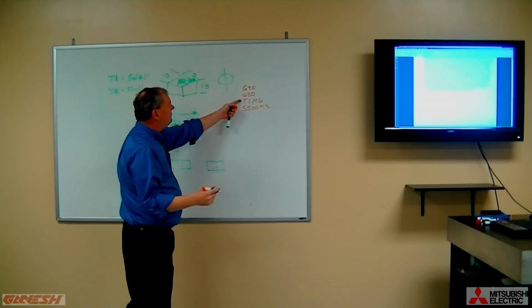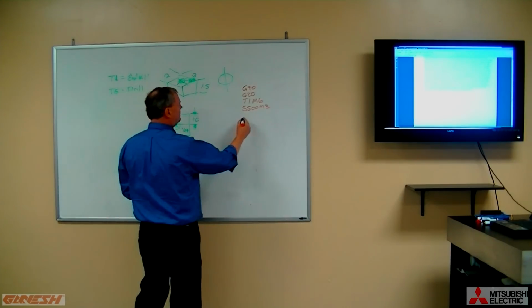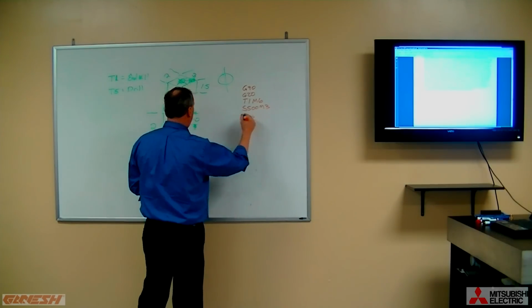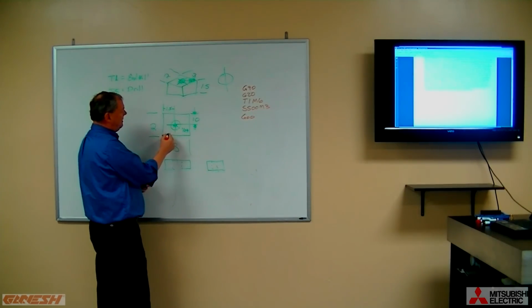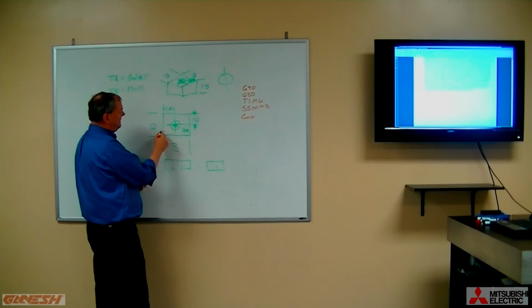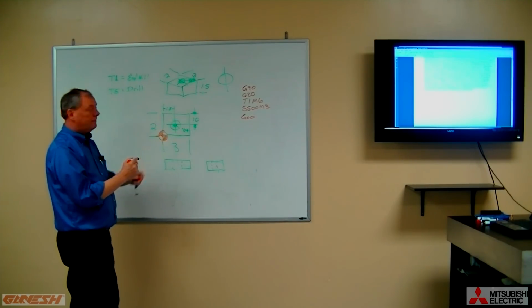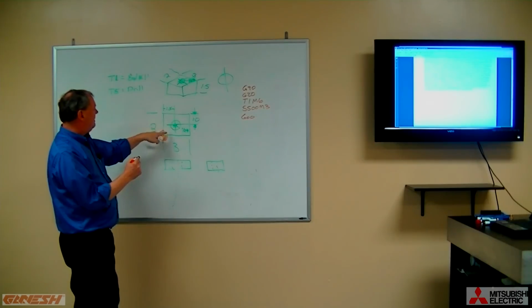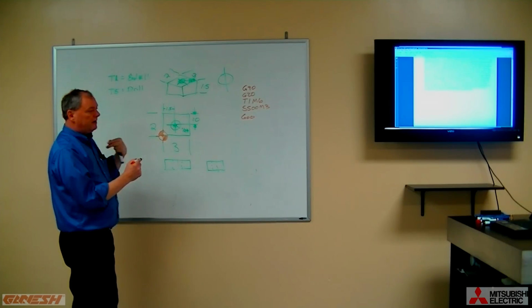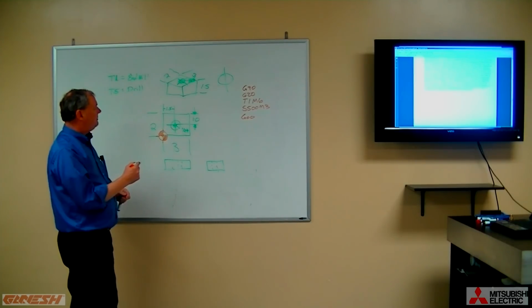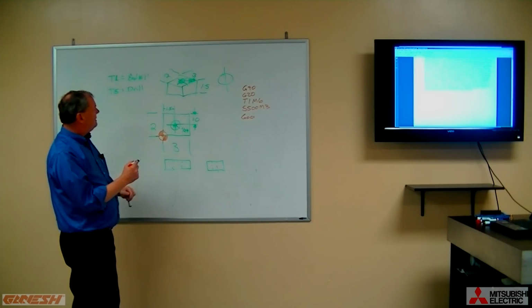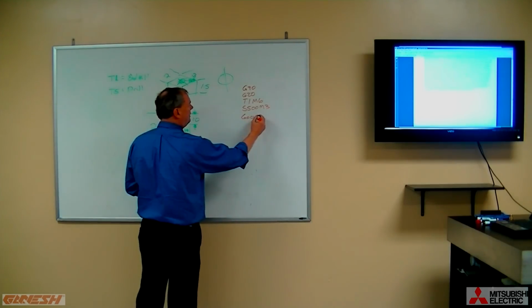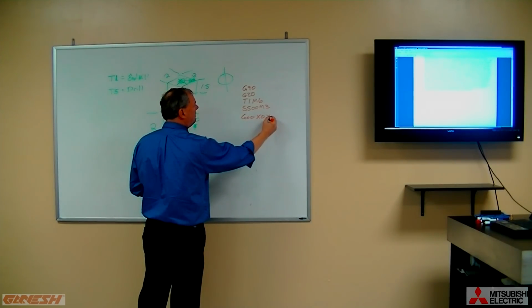And then if tool 1 is our end mill, we're now going to make a move. We're going to say G00. If we want to put it over this point right here, we'll assume that our program datum point is set right here as well. This is the point that we've decided to make our datum for this part program. If you remember, we can pick the datum. It can be anywhere on the part. That's up to us to choose where the dimensions are derived from. But now we're going to say G00 X0, Y0 to put it over this point right here.